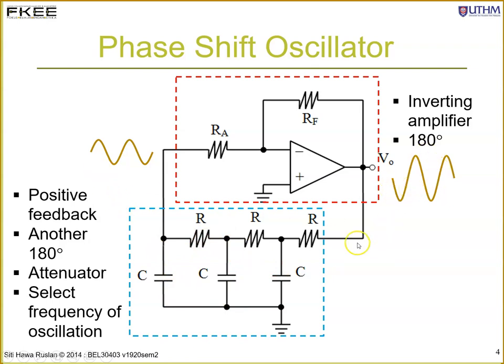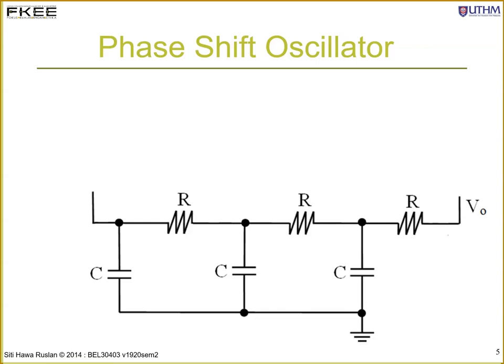Your output signal will be fed to this feedback network, and the signal will be lowered, okay, in terms of the amplitude, and it will be amplified again. So there is a closed loop, and this must fulfill the Barkhausen criteria of 360-degree phase shift around the loop, and beta, this is your beta, multiplied with the gain must equal 1. So this is what we'll analyze.